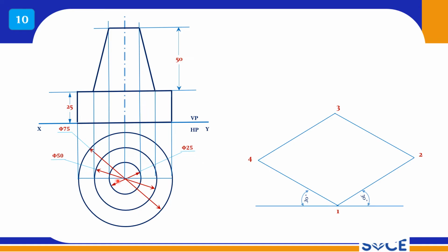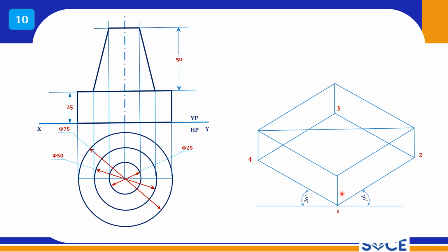So you can use the 4 center method very comfortably. You can draw this, right? So this 25 mm height should be taken here, and you should draw the top box. So this is the box, right? On the top box you mark the center point, and from the center you measure 50 mm and mark the top box.